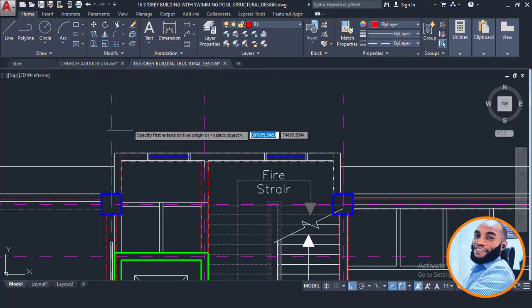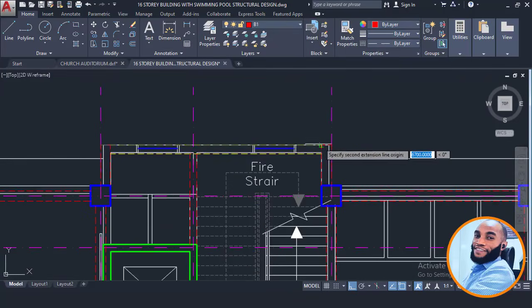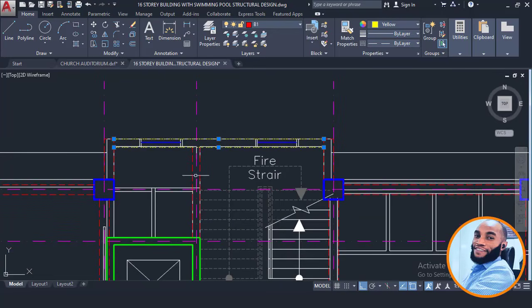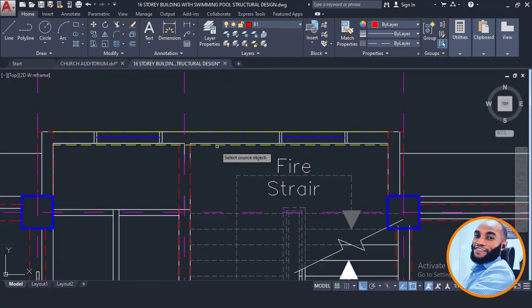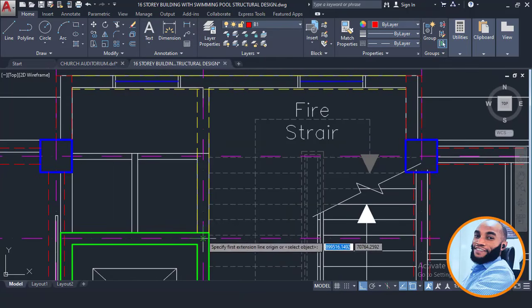I'll confirm from here what is the length from this point of grid to the point of grid here, to check this beam length along this place here. This gives me 7 meters, which is okay. Now since this beam here is supporting this beam here, I'll have to make this other one a secondary beam 2, secondary 2.